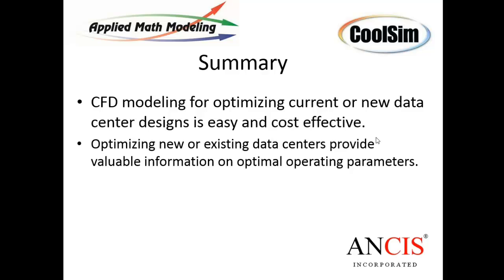If you know the inlet of the air coming into the room and its flow rate, and you know the rack and its consumption of air, you can calculate everything in the room through CFD. That's what CFD does. Where sensors are important is validating the model.